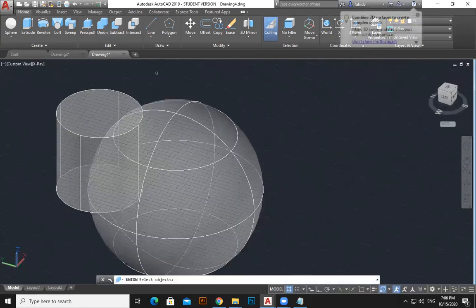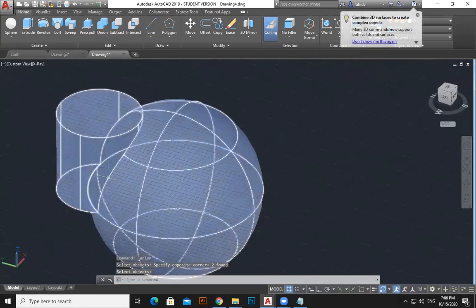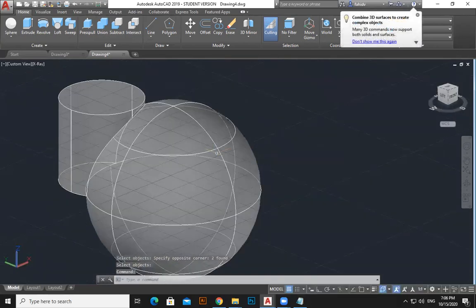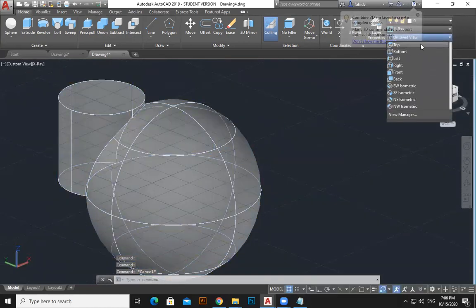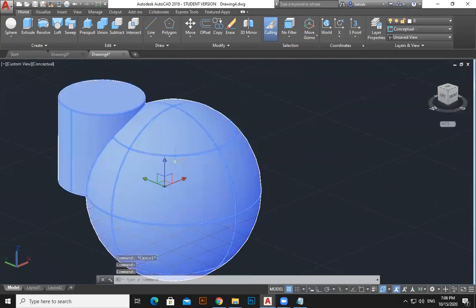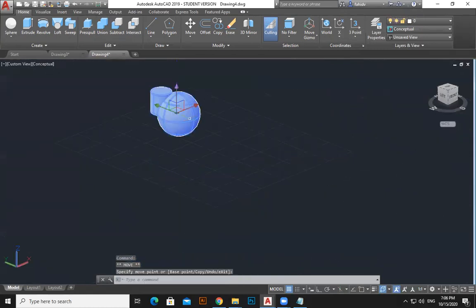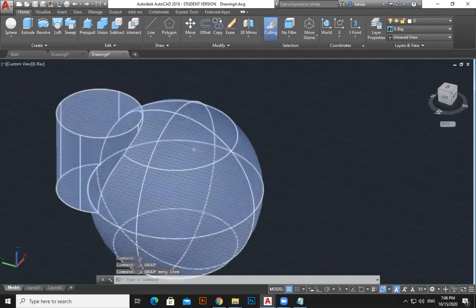If I do union, select both, enter. Can you see it cut inside? And it becomes a single object now. When I am selecting this object, it's a single object. It's like combining. Just select both and enter. That's all. But subtract means you have to select the one where you want to make the hole. That one, enter. Then the next object. That is subtract. And intersect means...